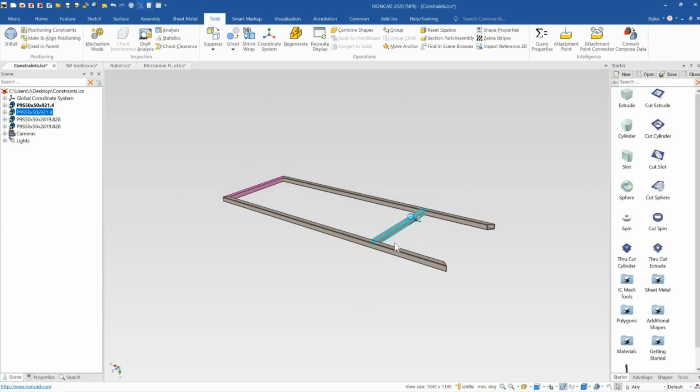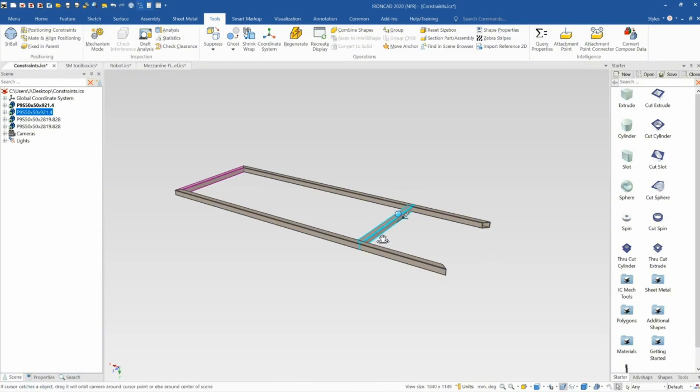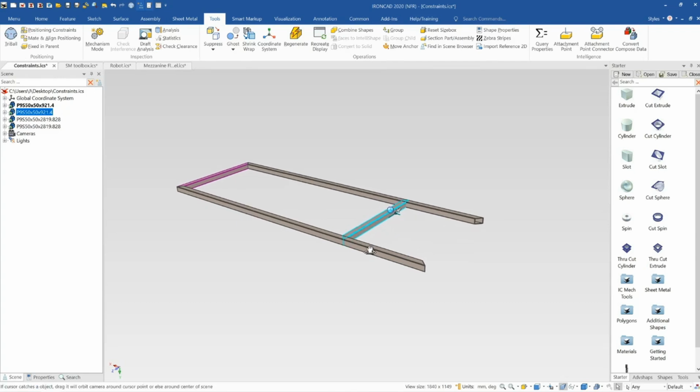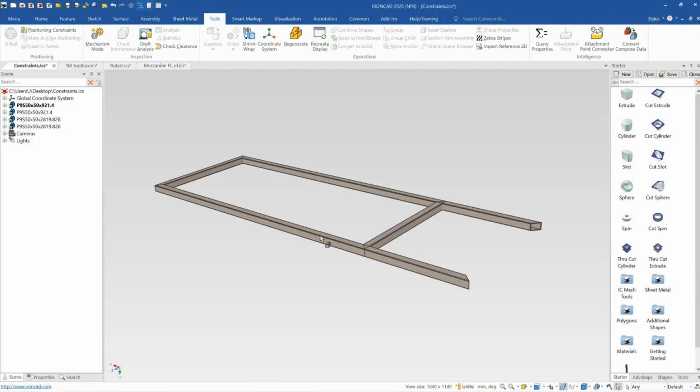assembly in the same file with everything already in the right place, positioned with the tri-ball. And then only when you have parts that you want to constrain their movement, you add the constraints to those parts and those parts alone, not the whole model. So of course, this can save a lot of time because you can skip a lot of mating and constraining that might be needed in a traditional system. So it's worth noting that mating and constraining shouldn't be seen as the norm, what you do with every model, just with specific models you'd like to simulate movement or you'd like to reuse, like we will with this frame.